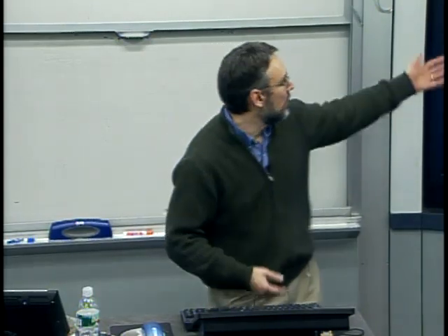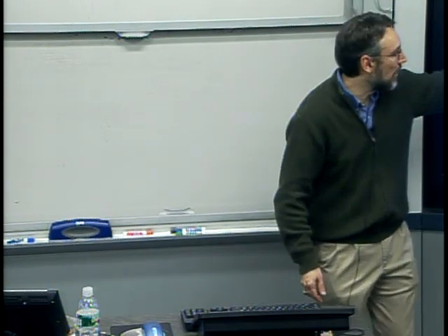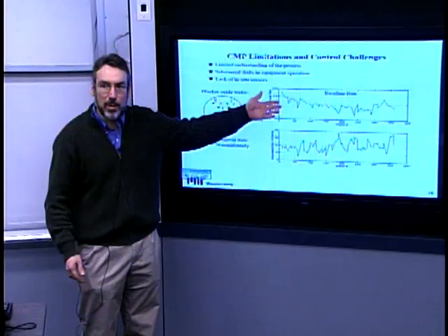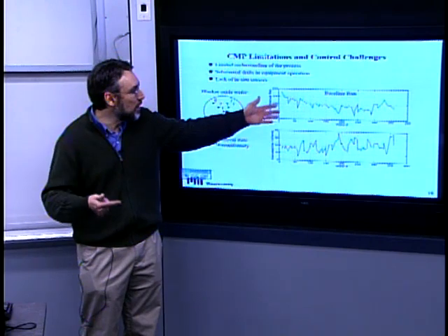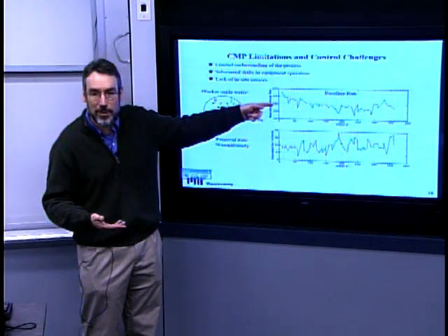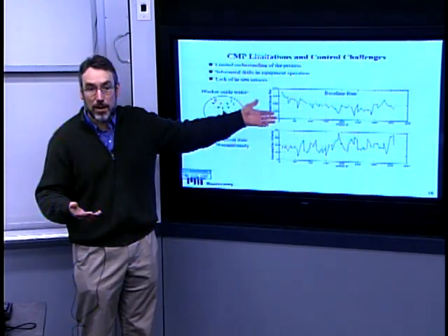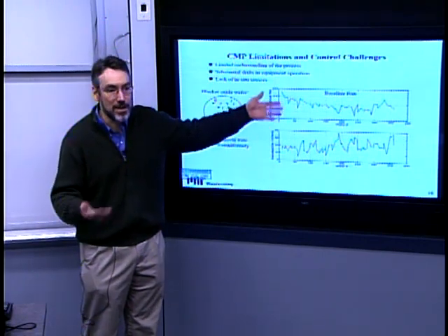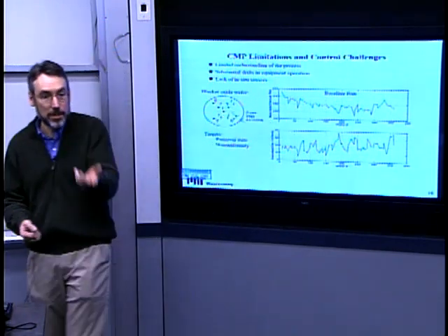I mean, basically, this kind of a drift, you could start to think, well, I can measure this, and maybe what I would like to do on subsequent runs, if my removal rate has drifted down, I'd like a strategy where I polish a little bit longer, or I press a little bit harder, these sorts of things.